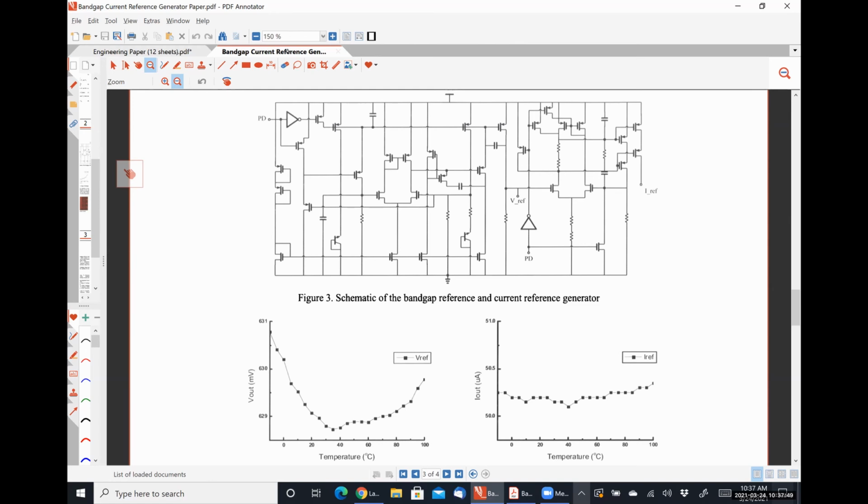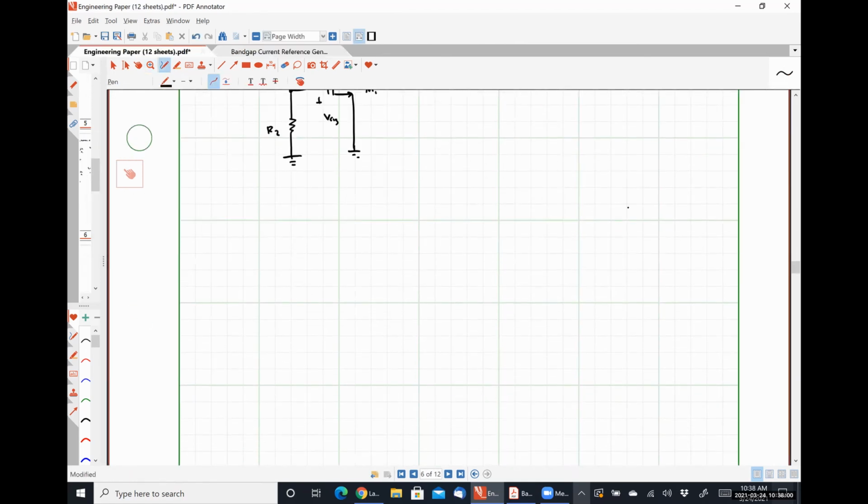So instead, what is done is what's called current mirroring. So in a current mirror, we have some reference current, typically supplied by a Bandgap reference circuit like the one we just saw, or something similar, depending on the application.